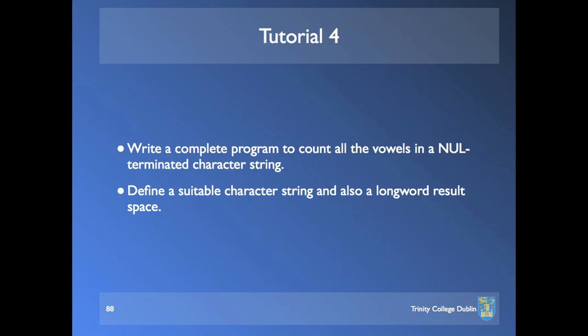And you choose these to suit yourself. You choose to use these conditions as parts of conditional branch instructions or other instructions to suit the purposes you have in mind. For instance, suppose you have 2 bytes and you add them together, and the result has the most significant bit of the byte equal to 1. Having added them together, the N bit will be set.